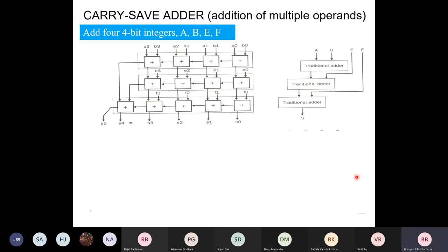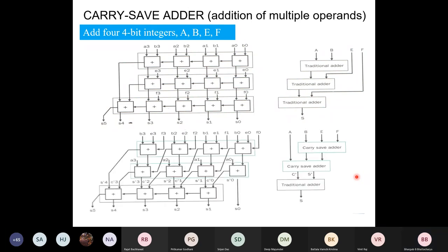So I'm trying to design my hardware in such a way which reflects the idea of carry save addition. Okay, let us look into this diagram. Here, as before, I have these 4 full adder blocks, but now notice that they are operating independently. There is no horizontal signal flow. Can you see it?